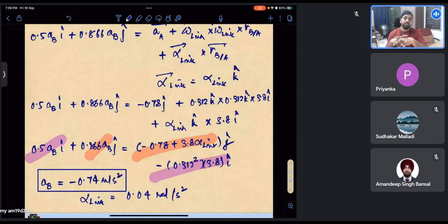See, the thing is, m plus r equal to 2j is a minimum requirement for us to keep it in equilibrium. But the arrangement of m is not captured in that equation. Members could be arranged in any way.